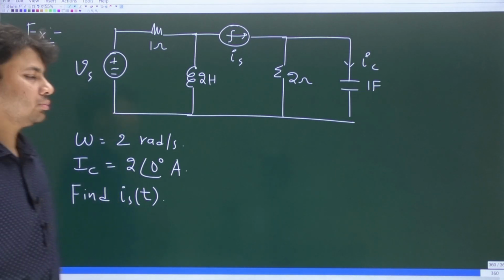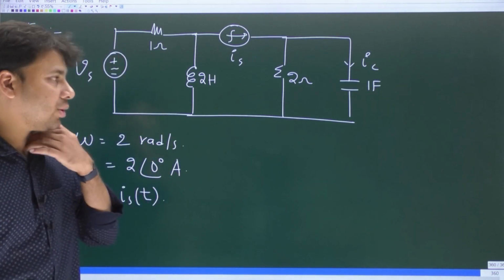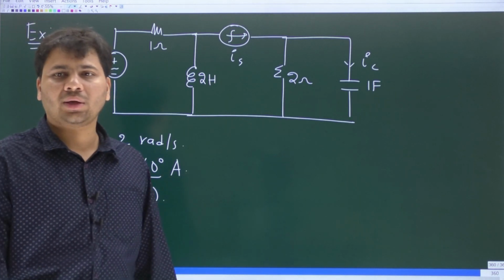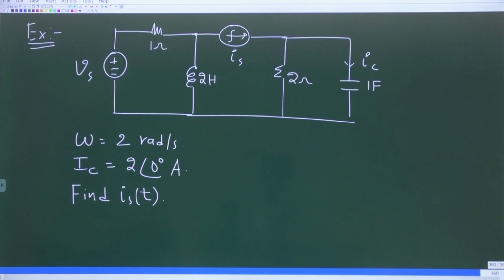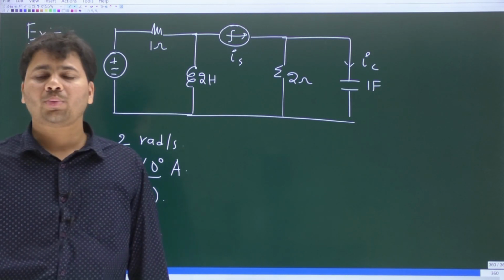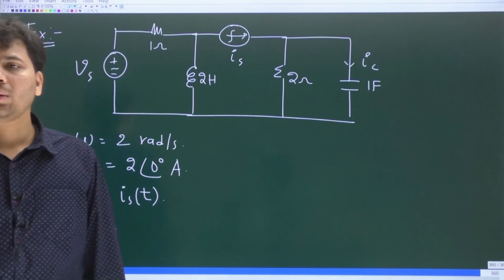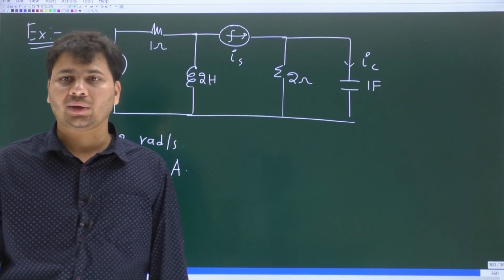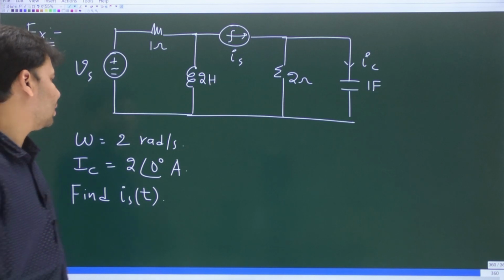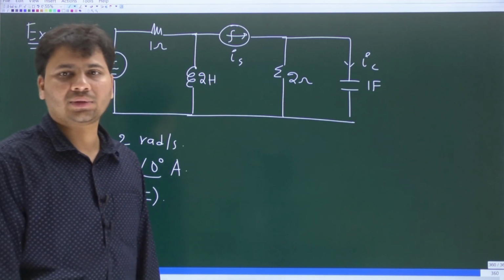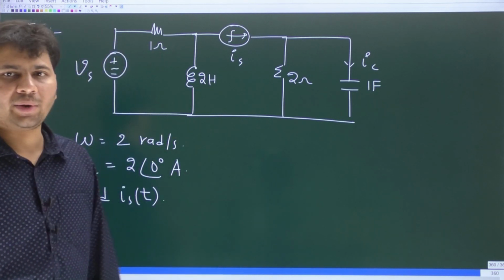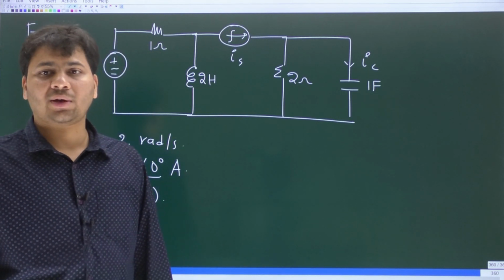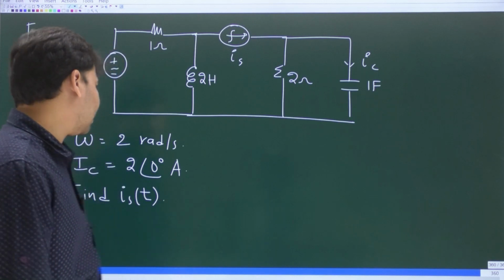Do it. You see, it's very simple. We just have to do the analysis in the phasor domain. Very good, Dineshwaran, what you got is correct: 2.06 at an angle, I think minus 14 degrees. Correct, right? So how do you go about analysis in the phasor domain? Whenever you are doing analysis in the phasor domain, you should first replace every element with its impedance.